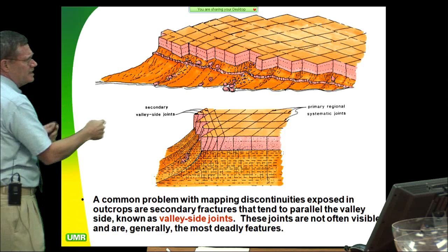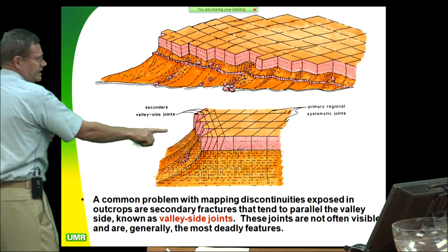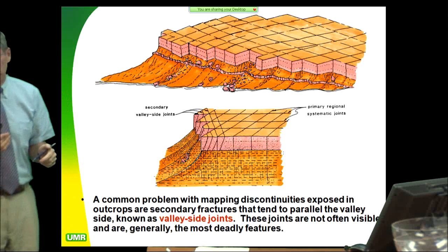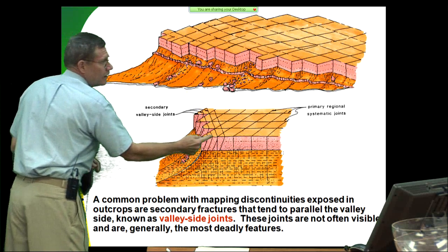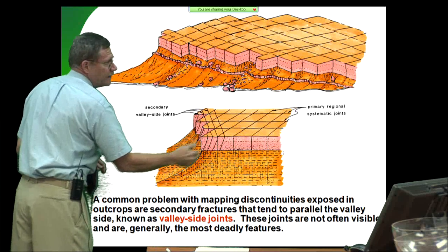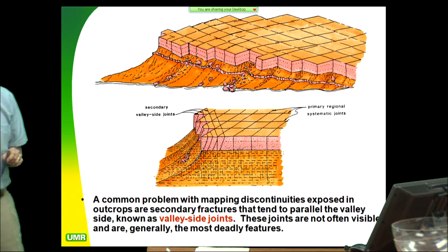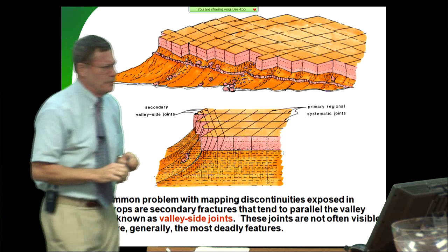So important. So you can't just set up over here on the other side of the canyon, take LiDAR pictures, and produce all this data. And the critical piece of data here are those secondary joints that are behind the face that you're not going to see on your LiDAR. So just, believe me, when you get out and practice, this is going to come home on you. It's really going to come home on you.